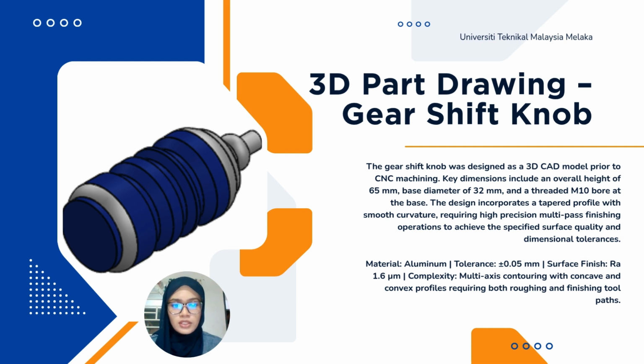Moving to the next one, this slide shows the 3D CAD model of the gear shift knob created before machining. The part has an overall height of 65mm, a 32mm base diameter, and an M10 threaded hole at the base. It features a tapered shape with smooth curves, requiring both roughing and finishing operations to produce accurately. The part is made from aluminium with a machining tolerance of ±0.05 mm and a required surface finish of 1.6 micrometers.